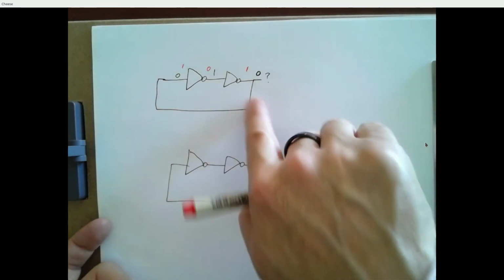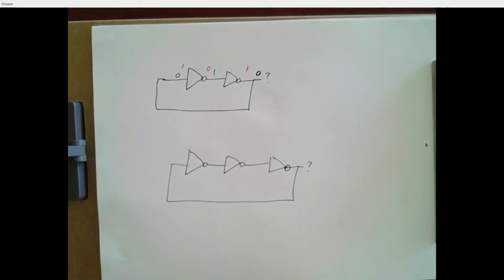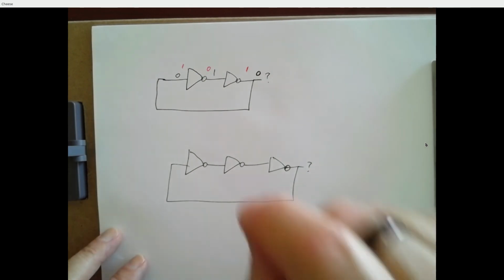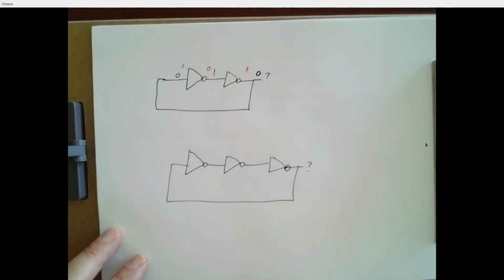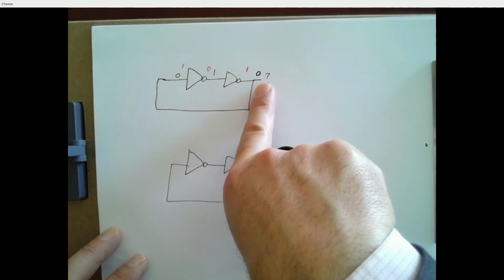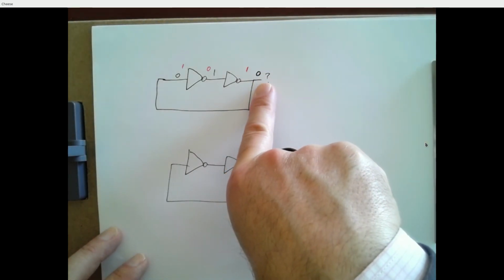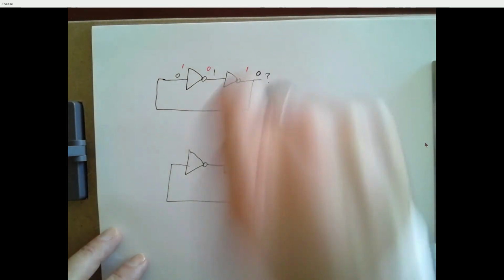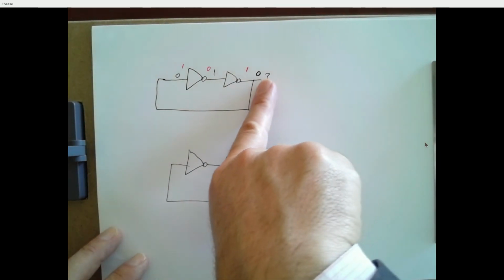And we didn't control whether that was a 0 or a 1, but in fact if you build this and you take a wire connected to 5 volts and you really briefly just tap it to that point on your circuit and then take it away, this output will go to 5 volts. And then if you take a wire and connect it to ground and you really briefly just tap it right here, this will stay at 0 volts.